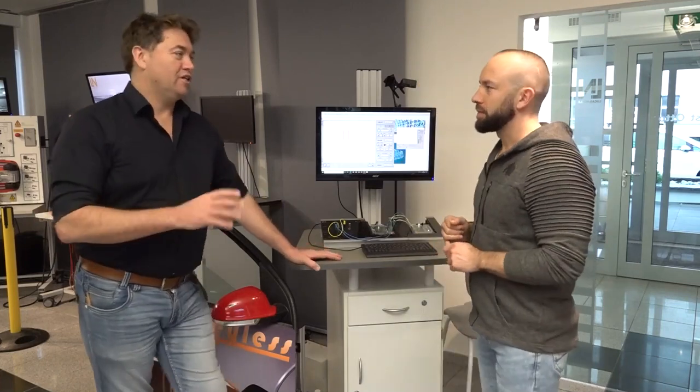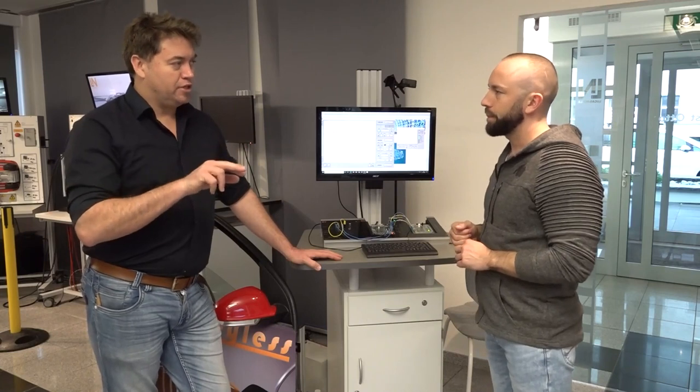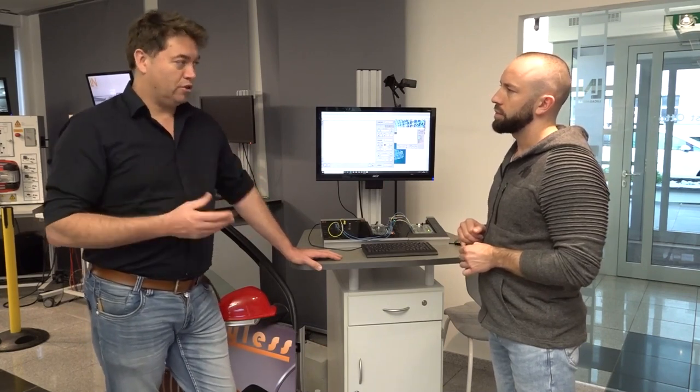Yeah, and that's the OBD plug. Having access to the CAN pins there, you're seeing a high-speed signal, and it's only certain messages. So it's one way to see if the system is operational. But if you look around the vehicle, there are lots of different CAN networks, not just one.